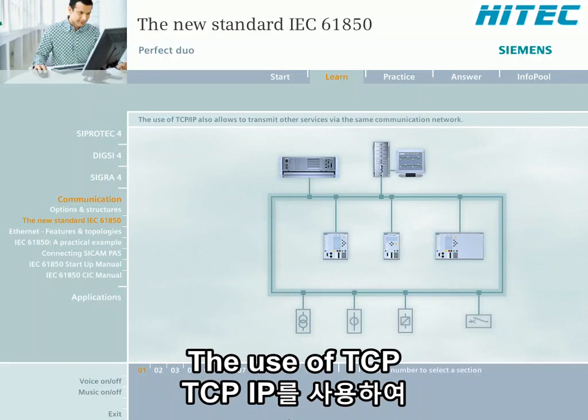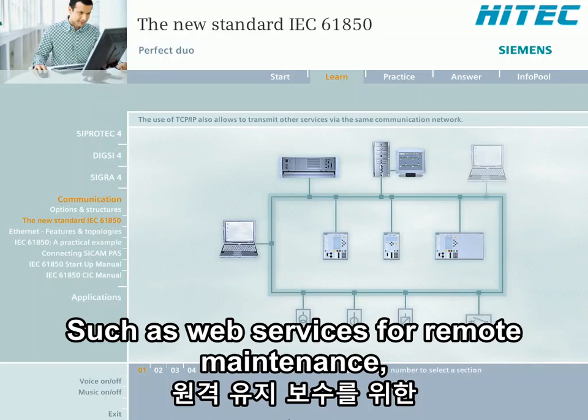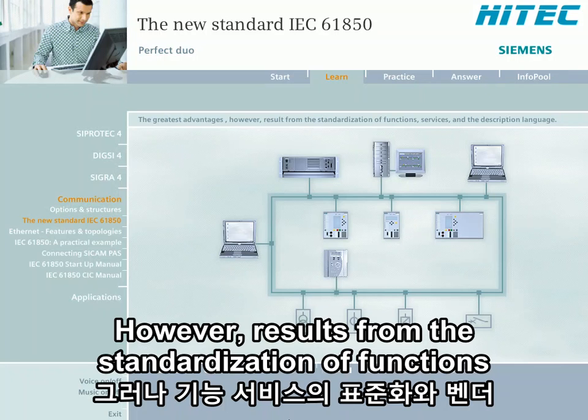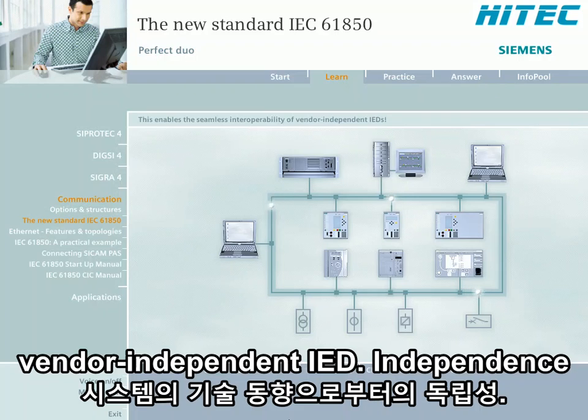The use of TCP/IP also allows to transmit other services, such as web services for remote maintenance, via the same communication network. The greatest advantages of IEC 61850, however, result from the standardization of functions, services, and the description language. This enables the seamless interoperability of vendor-independent IEDs.